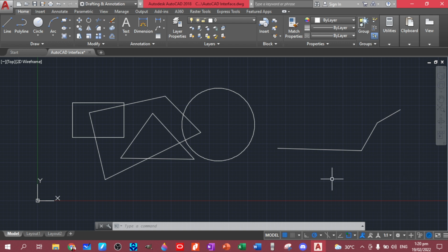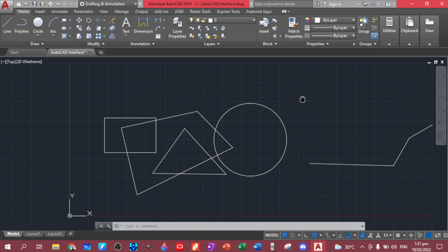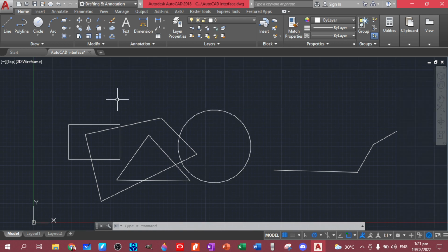So there is also another option when you want to click your lines by navigating your cursor towards that object or your line. Click it, then you can actually select that one. Click, click. To unclick, to undo, you can just use escape. Now, for a bigger scope, there is what we call the selection window. Let's try first the left to right. So, in your mouse, you click your left button, then you navigate.